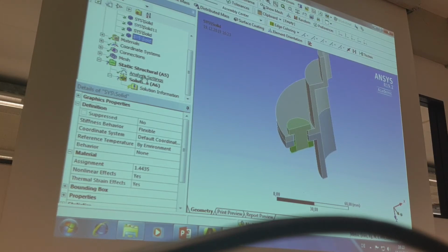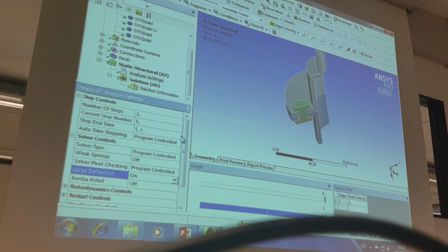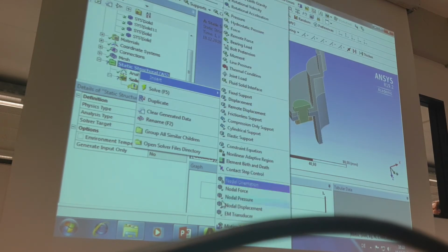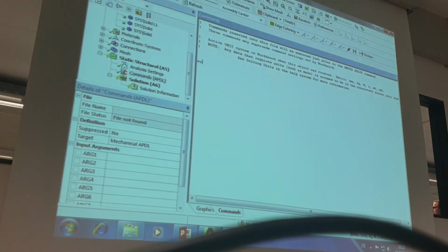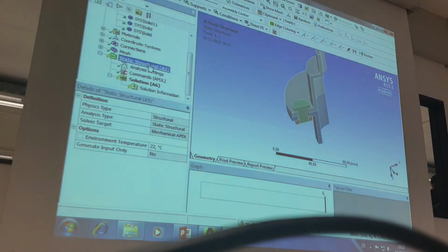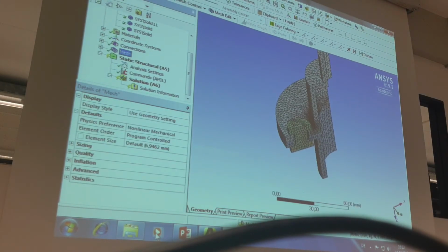Material properties, then we have to define large deflection on. It means the program always calculates the new geometry. Yes, geometry is changed during our calculation. Yes, if I pull one beam, then this beam will be less in diameter. So my geometry is always changed. I say on, then I have to insert a command, then we have correct results. Okay, every point costs calculation time, but it's better than calculating a wrong simulation.